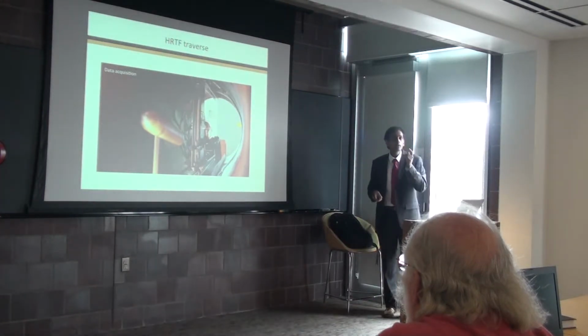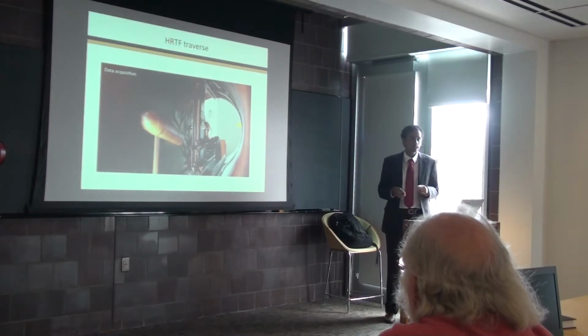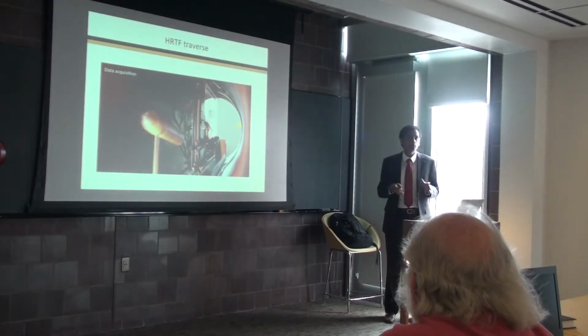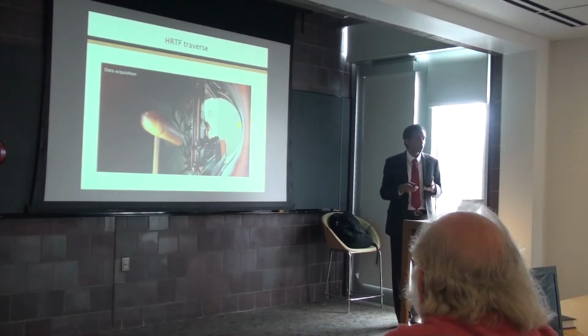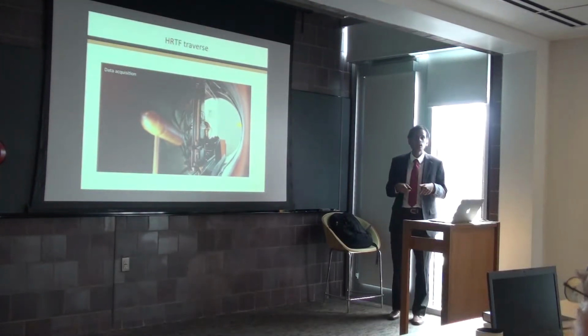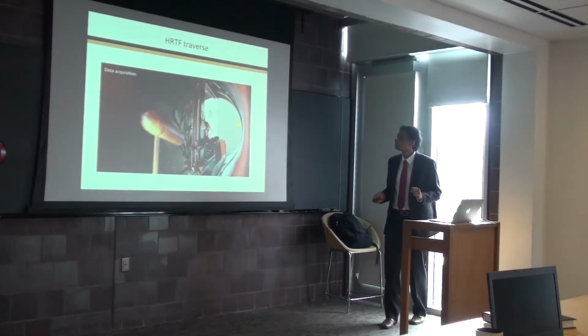I mentioned to you before that the previous data was taken with optical techniques. Of course, we would need optical access for that. This is a hermetically sealed pipe. There's no optical access. So we rely on traditional methods, hot wire anemometry and point measurement techniques, to be able to study this wake. So we will only be able to look at the mean and statistical quantities in this structure. We won't be able to look at instantaneous behavior.